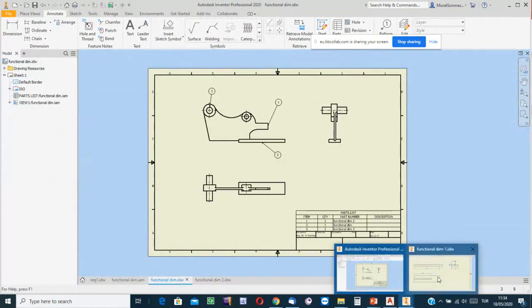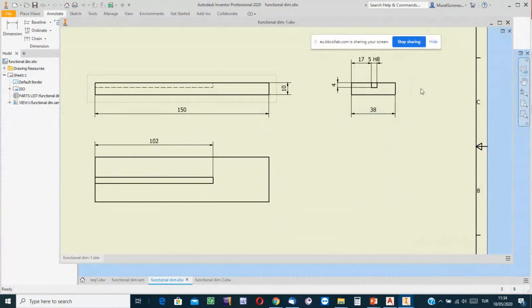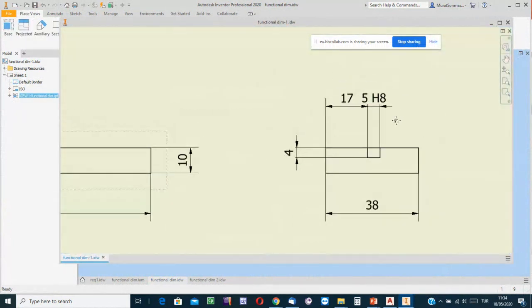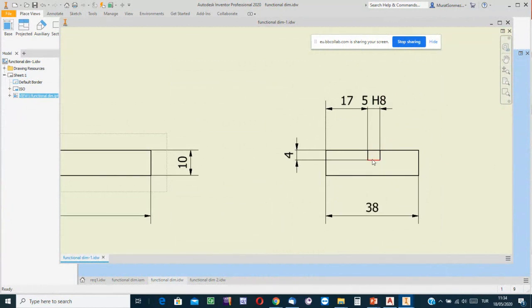Where is it? Yes, here it is. You see, the dimension shown here on the left side view is to inform the reader and technicians of the size of the channel: the width and depth of the channel is 5 millimeters. Pay attention, please. 5 is the nominal value. Showing the dimension of the channel on the technical drawing of this component, we write the same nominal value.